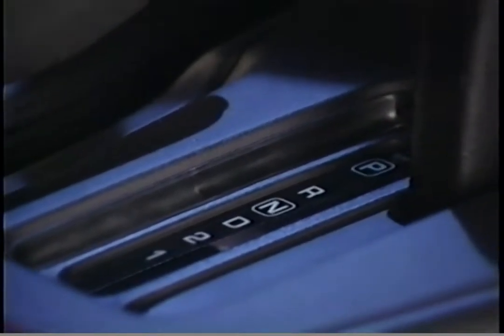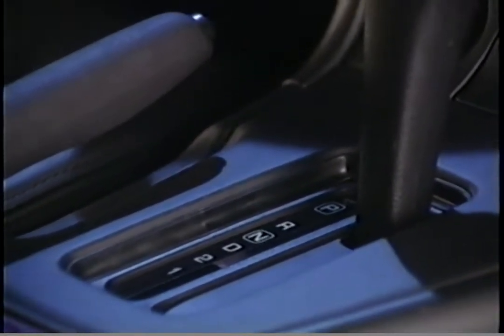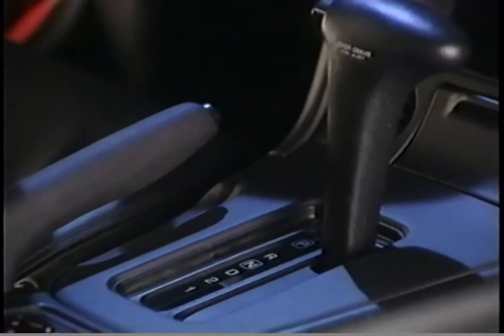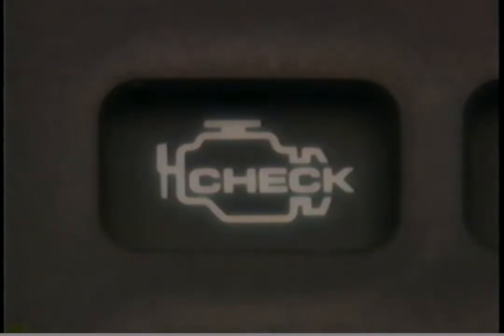Malfunctions in the automatic transmission will not only trigger codes in the Transmission Control Module, or TCM, but also in the Engine Control Module, or ECM, where they will be recorded as related to OBD-II. Problems will be signaled to the driver by illumination of the malfunction indicator lamp, or MIL. Remember, with the expanded functions of OBD-II, the MIL can be triggered not only by open sensor circuits, but also by sensors or systems which are not operating within their expected ranges.